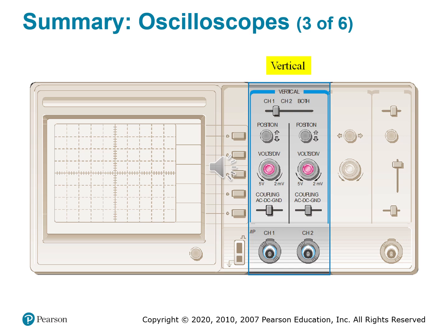The position knob, this moves the waveform up and down on the screen. It doesn't affect the signal. It just shifts your viewing window, which is great for comparing two signals or centering your trace.